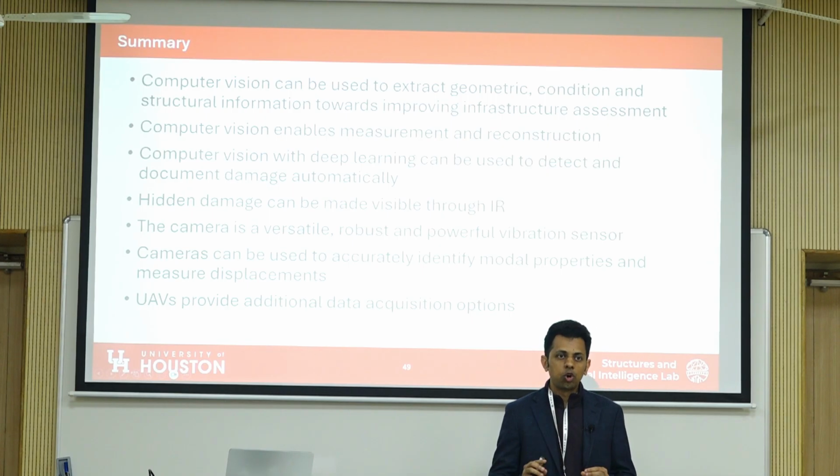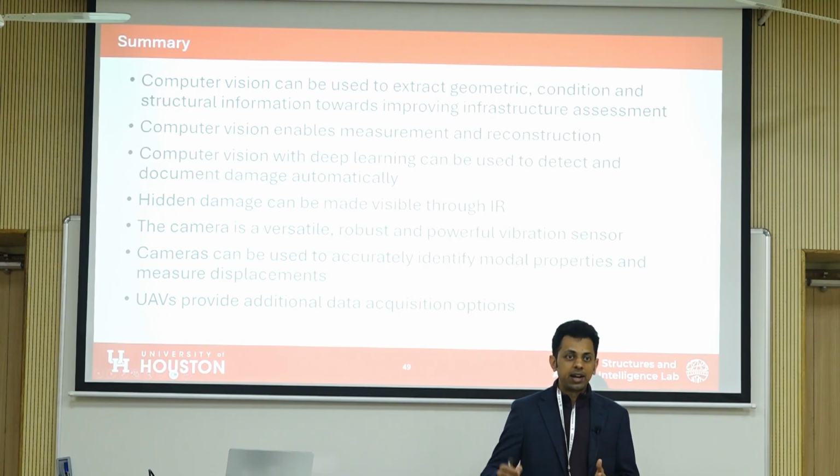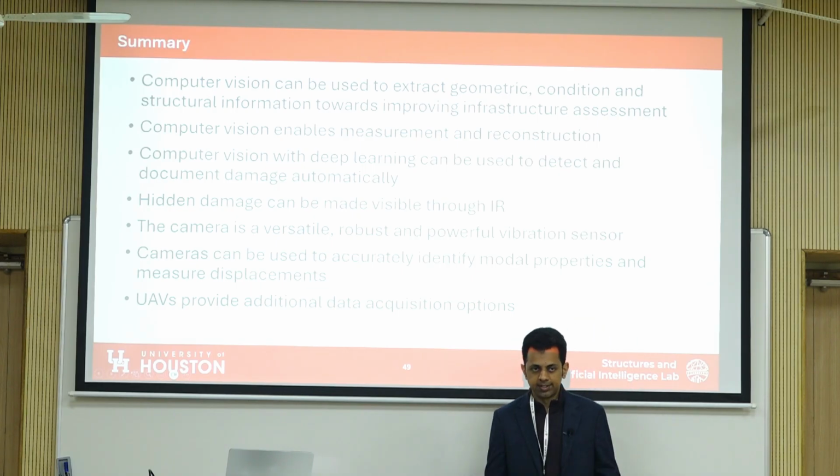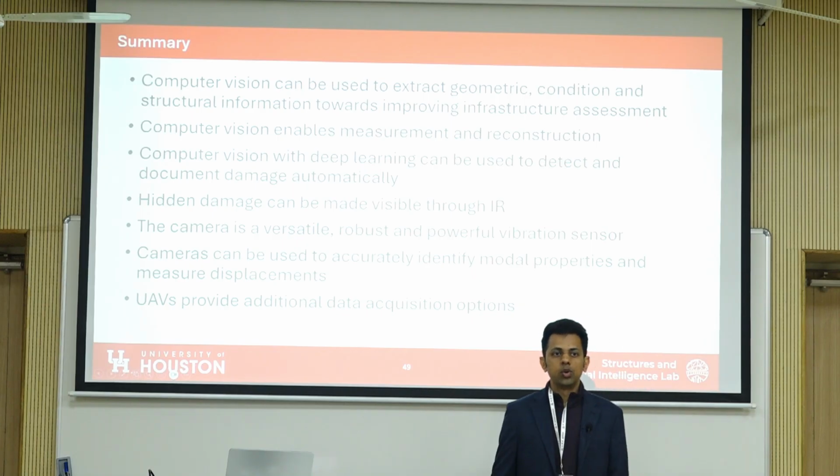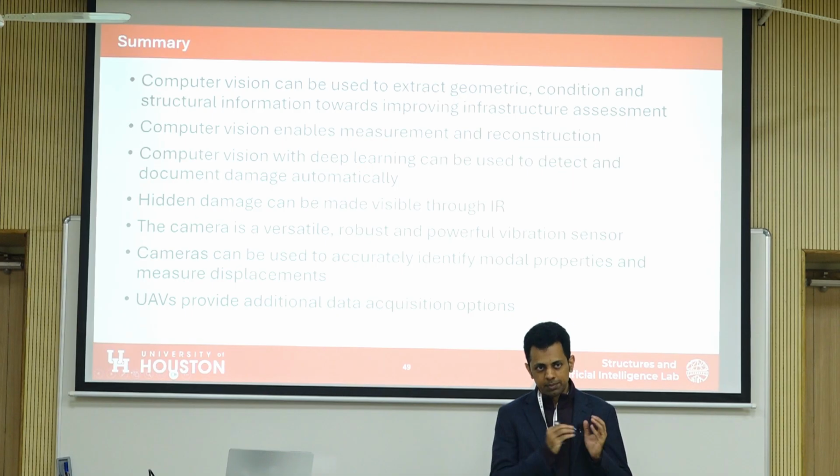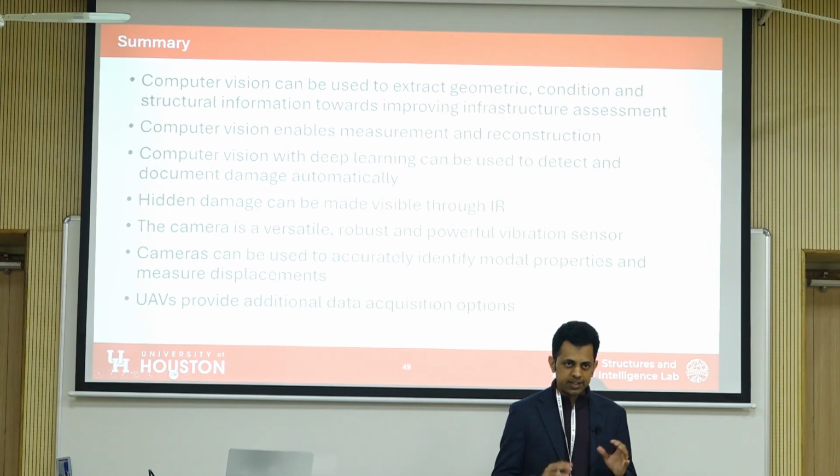Now, there's no fixed answer to your question. It all depends on the specific structure that you're looking at, and very, very importantly, what your objective is when you are collecting the data. Because the objective is going to drive all of your decisions. And so you need to decide first, are you looking for damage? Are you looking to create a 3D model? Or are you looking to measure vibrations? All of those decisions have to be made first. And then, looking at all of the legal restrictions and all of the safety restrictions, you can then maximize your objective of whatever data you're looking to collect.